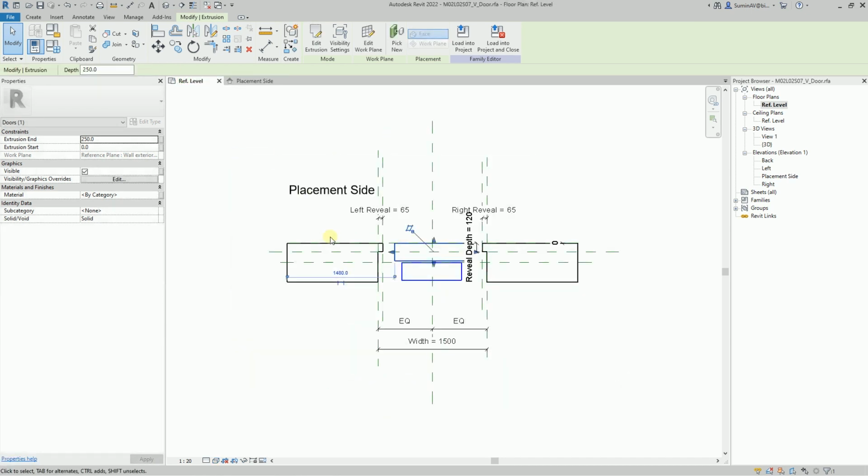We see that it is created precisely from this plane. Its height is built inward from it, in the same way as it was with the first extrusion element. Strictly speaking, this moment depends on the way we build the reference plane, from left to right, or from right to left, from bottom to top, or from top to bottom.